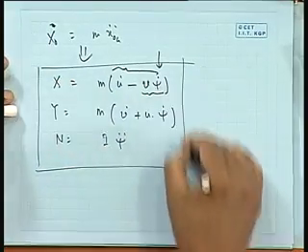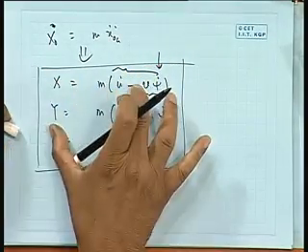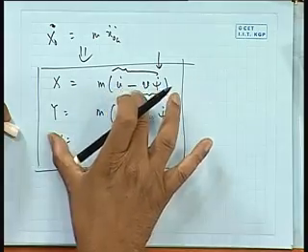That means u is the velocity along the ship's instantaneous x axis, which is itself changing, and because of that you get extra terms. So we end up with this equation of motion, which will be the starting point for our next part of the lecture, simply by writing the equation of motion with a moving body-fixed coordinate system. That is all. Thank you.